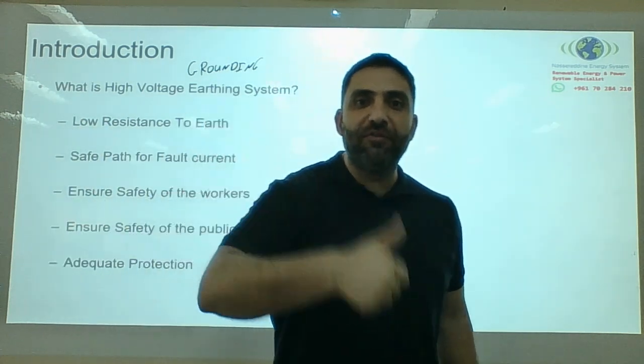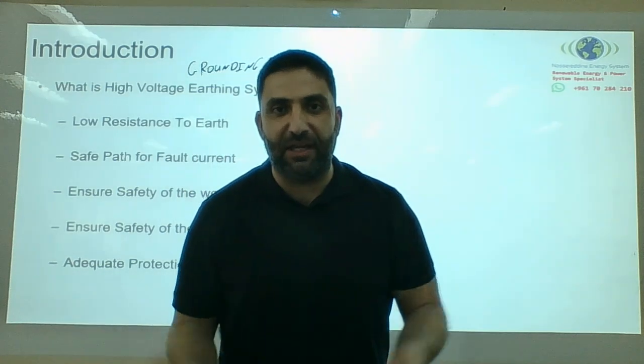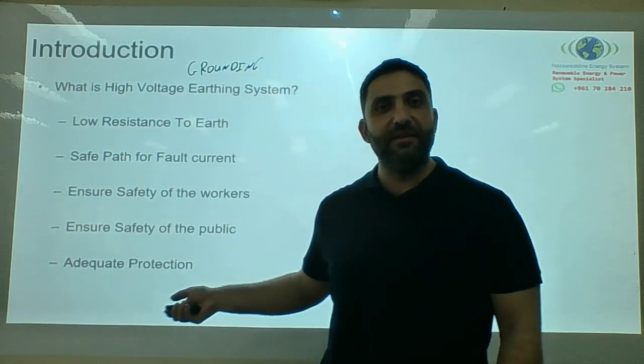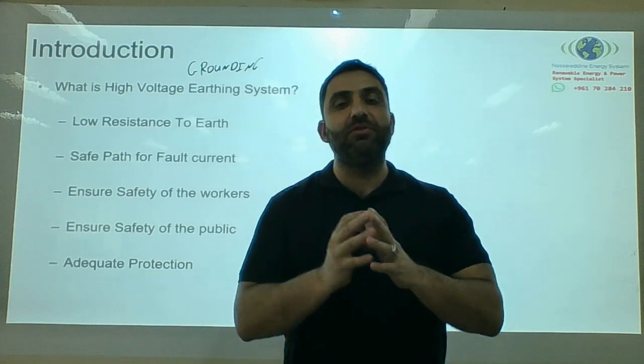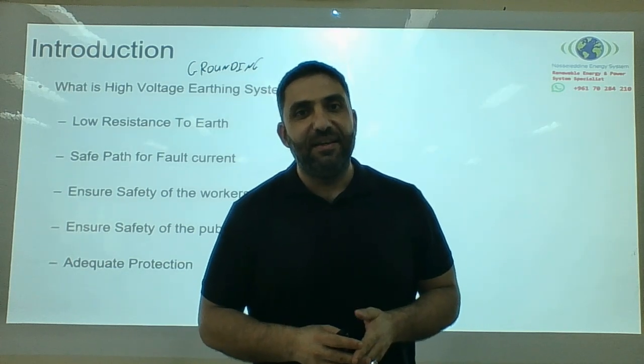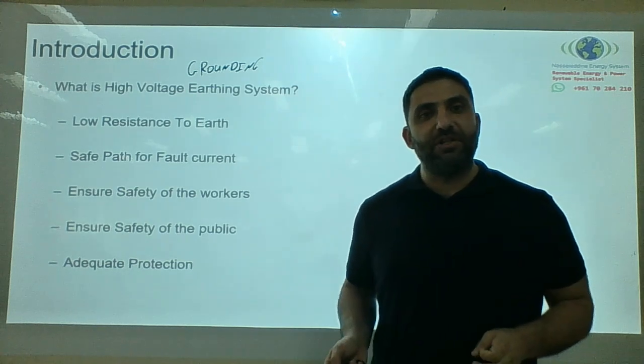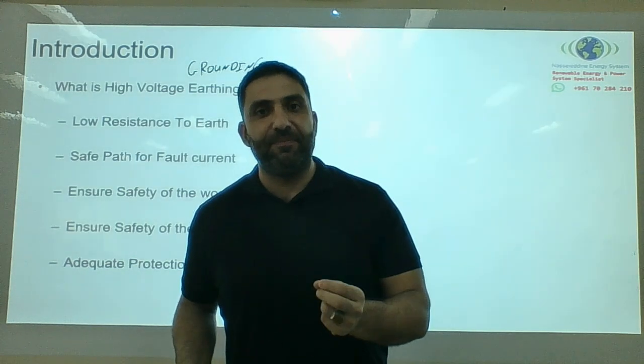So if you have an overcurrent relay, or any type of relay that requires an earthing system, requires reading the resistance, of course this plays an important role. It's very important for the protection to have an adequate earthing system.